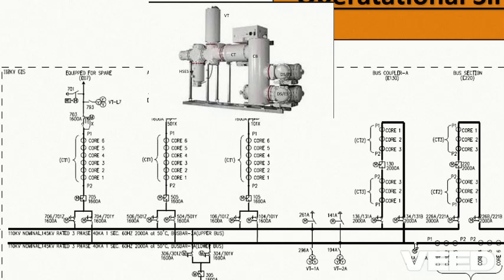Then there's the line isolator. Line isolator actually provides the facility to be ready for the energization, and it will give you an option to isolate the bay from the line or to connect the bay with the line. Before closing the breaker,